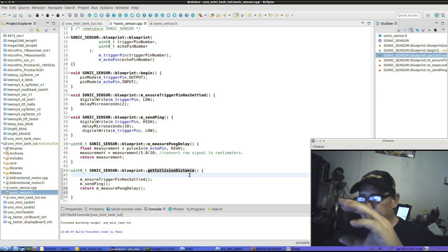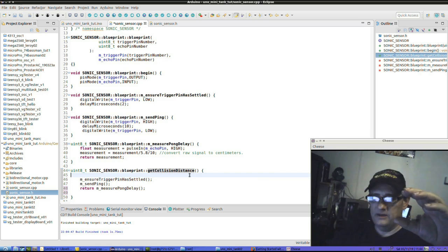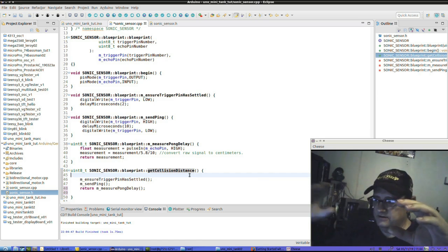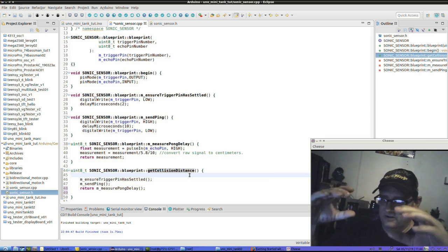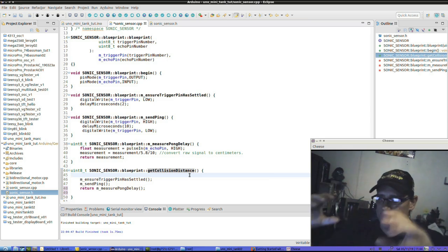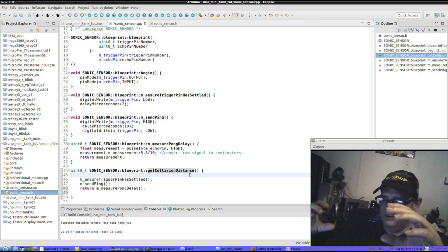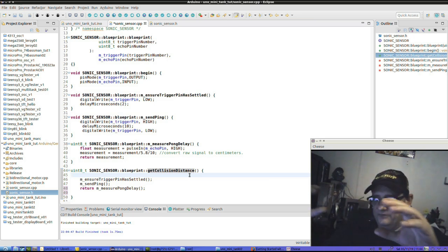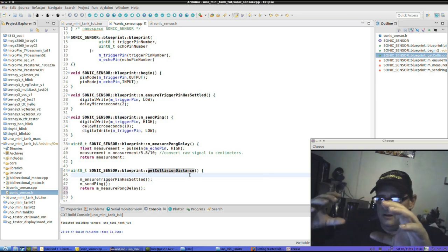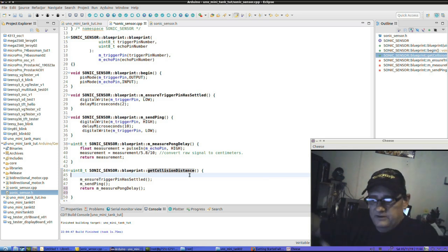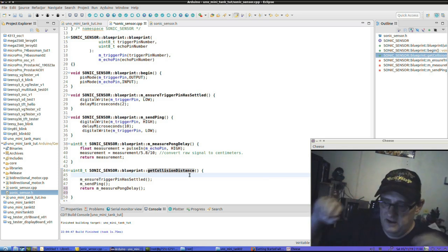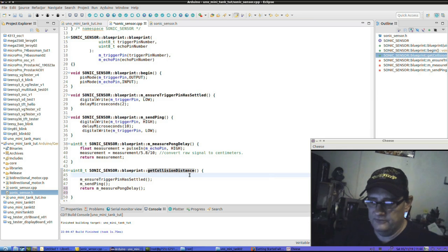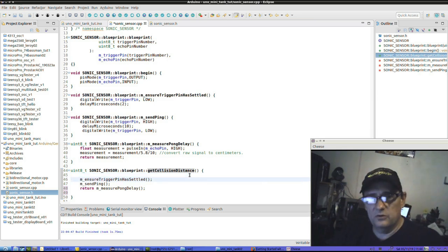In other words, measure it, remember that information, measure it again, and then are these two equal? If they are, it's probably good data. If it's not, then store that over here and then measure it again and see if they're equal. And if not, well, save that and then check again. And once those two are equal, in other words, you keep checking until you get this one and the consecutive next one equal to each other, and then you can rely on that. So that's what I've been doing, and that works quite well, actually.